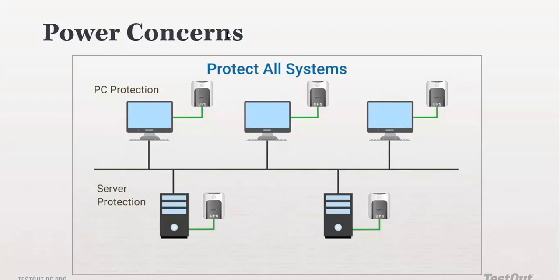You don't want to have a situation where you have 3 computers connected to one UPS. It's going to speed up the drain time by 3, and you find yourself using a UPS that was supposed to be used for 3 hours in 1 hour, and the battery is drained completely. So you want to have one UPS per device to maximize the time out of it. This is for a scenario where budget is not a problem and data sensitivity or confidentiality, maintaining data online, is very important.